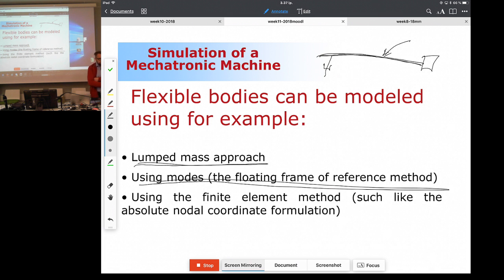All the commercial software like Adams, RecurDyn, and SIMPACK, which comes from Germany by the way, are capable of describing deformable bodies, and typically they do that using the floating frame of reference formulation, based on the combination of a finite element model and multi-body system dynamics. But there are special formulations, such as the absolute nodal coordinate formulation, that can also describe the deformation.